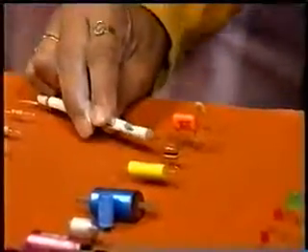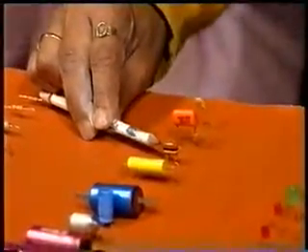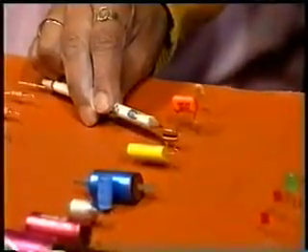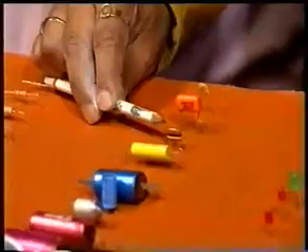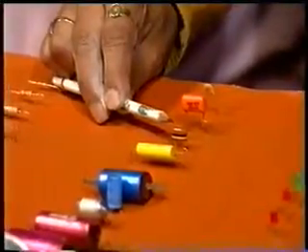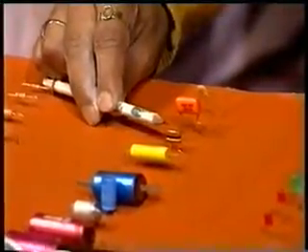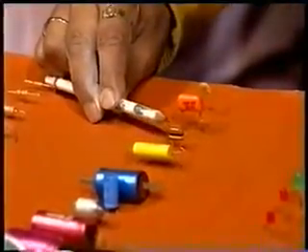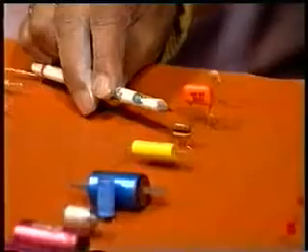Now let us come to this particular capacitor. This is also a polyester type of capacitor, but here you find that there are certain color bands, like you had in resistors. The first band is brown, then black, then yellow, then again brown, and then orange. Now brown, as you know, stands for 1. I write 1.